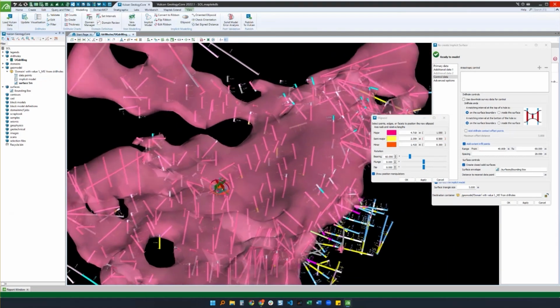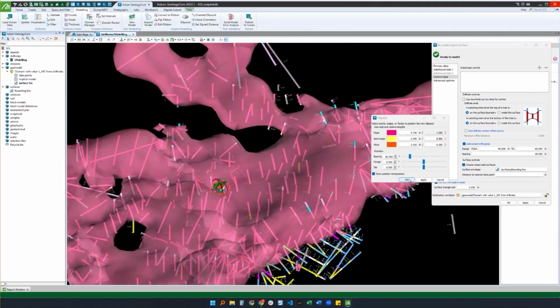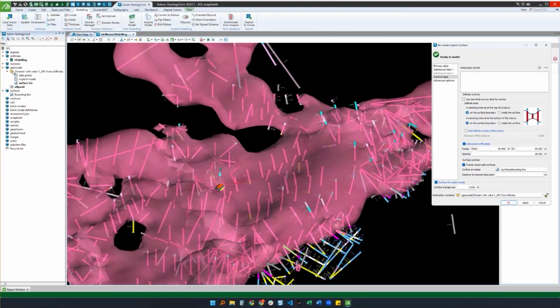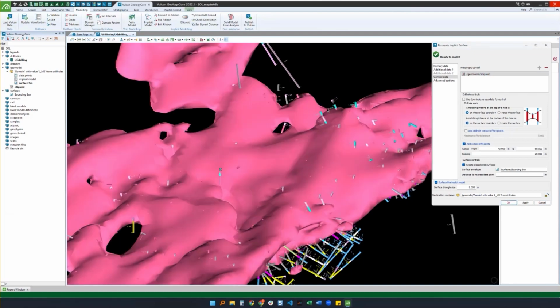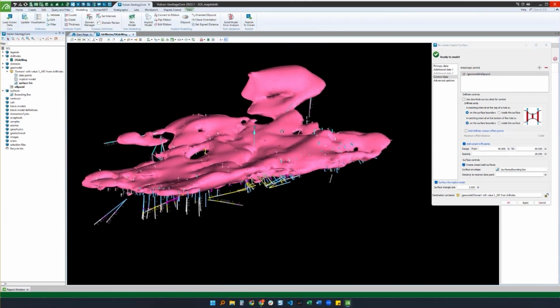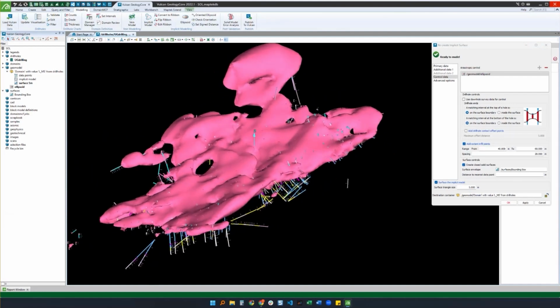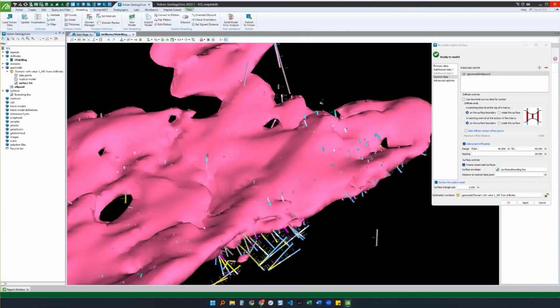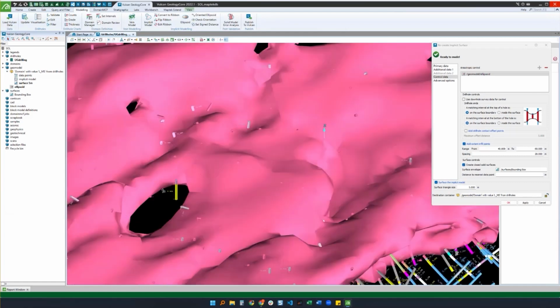And that's not too bad. So I can select OK and it will create that ellipsoid in the GeoModel container for me. Now I can use my middle mouse button and drag that off the screen into the anisotropic control component. And now if we rerun that, you can see my model is a lot more continuous in that orientation and has less holes,